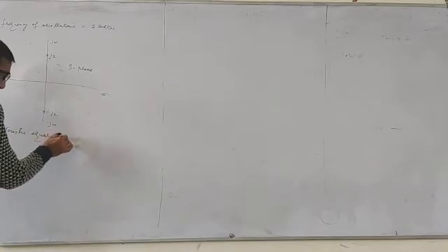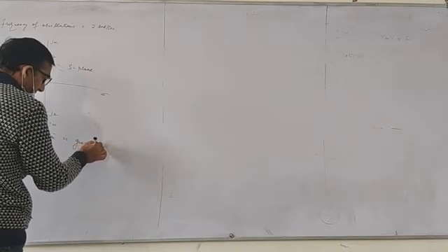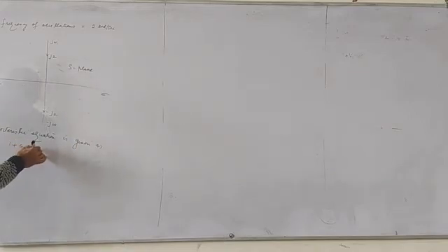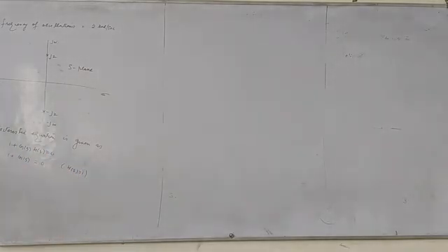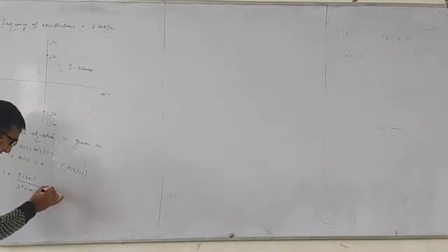Okay. So next, the characteristic equation of the feedback system is given as 1 plus g of s, h of s is equal to 0. Since h of s is unity for a negative feedback system, 1 plus g of s equals 0. G of s is given: k times s plus 1, divided by s cube plus a s square plus 2s plus 1. That should be equal to 0.